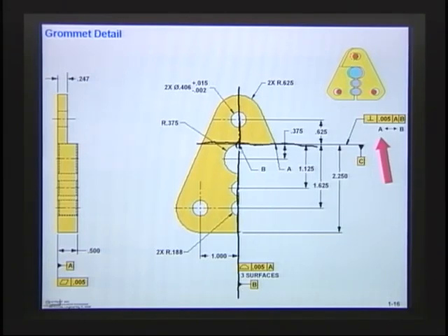Right? This is the origin of the coordinate system. And you notice that when we put this profile on over here, what that does is it allows this one to be off a little bit, allows this one to be off, allows this one to be off. I have this tolerance zone here. It's really not a plane that goes all the way across because there's only 3 surfaces.